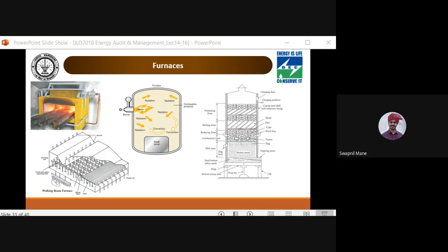The flux also melts and reacts with impurities of the molten metal, forming a slag. You see there is a slag layer here. This slag floats on the surface of the molten metal, and it prevents oxidation of the metal. There are different zones of the cupola furnace, such as the well zone and the combustion zone. All reactions taking place in the combustion zone are the oxidation of manganese and silicon, which evolves heat, whereas in the melting zone, iron gets converted into iron carbide.